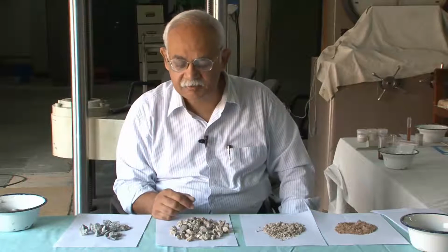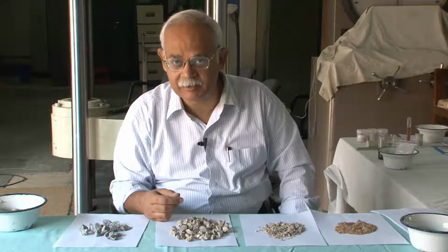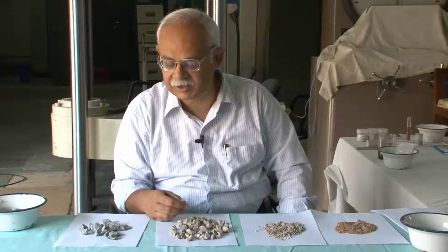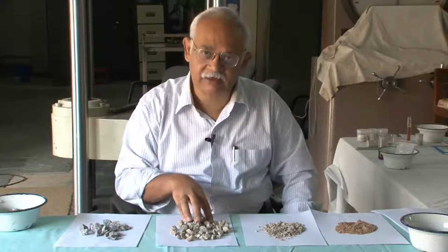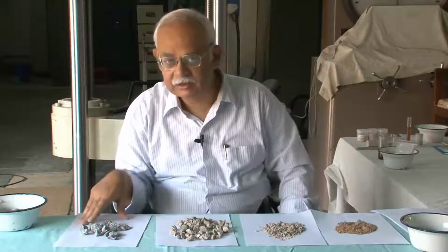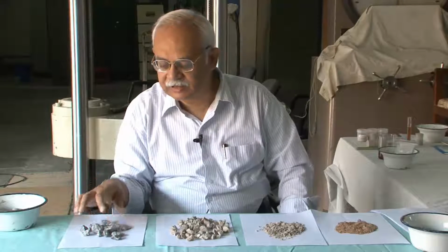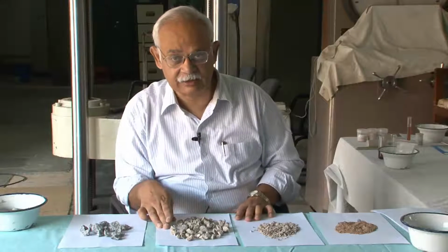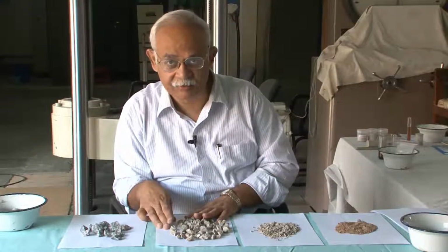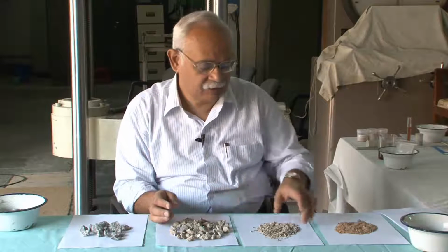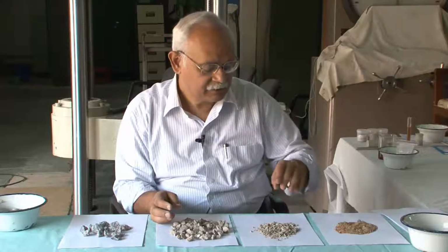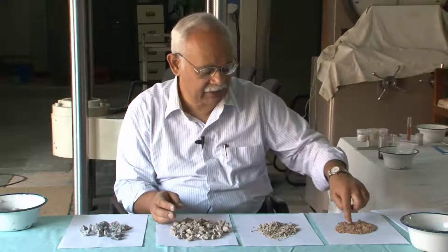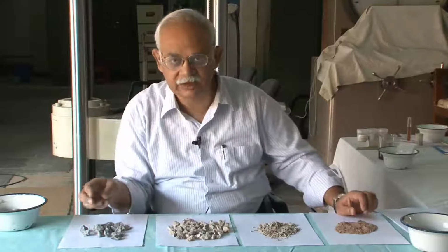There is a difference, but yes, they can be used at least in certain applications, and the challenge is to identify the proper applications where we can use this kind of recycled material rather than using virgin coarse aggregate, which is shown here. So, recycled concrete gives us an option in terms of coarse aggregates which have a certain size distribution, and also fine aggregates which has another size distribution much smaller, and this is what is comparable to sand, and this is what is comparable to coarse aggregates.